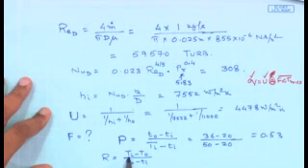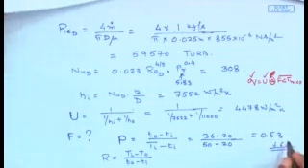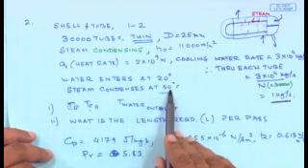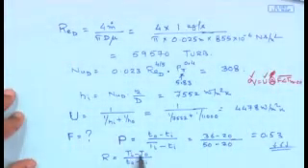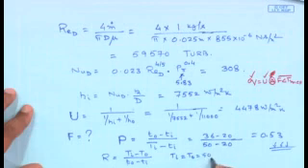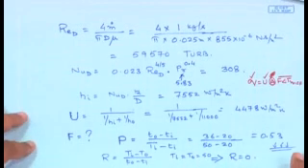Now, if you see, for the case of steam condensing on the outside, the steam is going to condense on the tubes at a constant temperature, and it's mentioned that the steam is condensing at 50 degrees centigrade. So, therefore, the value of Ti and T0 are equal. Ti is equal to T0 equals 50 degrees, which essentially gives you the value of R to be equal to 0.